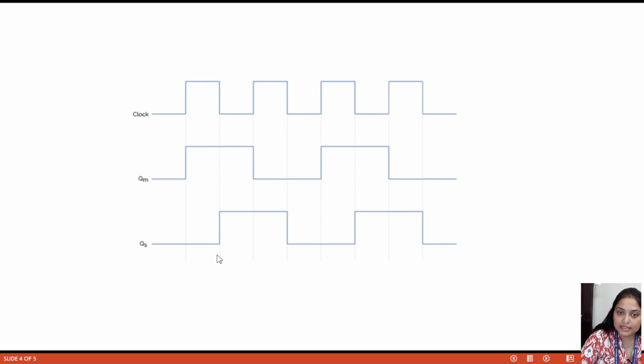And this is the clock output, so this is the negative going clock pulse. The slave works on the negative going clock pulse. Basically, when the clock pulse goes from 1 to 0, it starts working, and again at the next negative going pulse, when it comes down from state 1 to state 0. So in this way master slave flip-flops work.